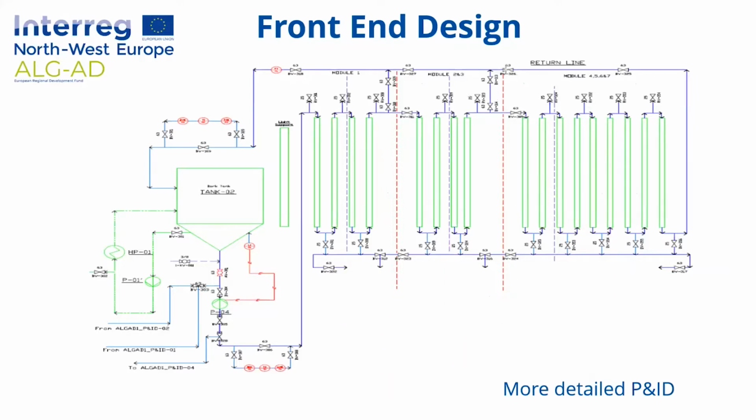And what that does is it basically facilitates cell line scale up, and also means that you don't need a large inoculum, typically something around about 10%, maybe 20% of the total reactor volume. You can basically scale up in stages, which helps a lot.